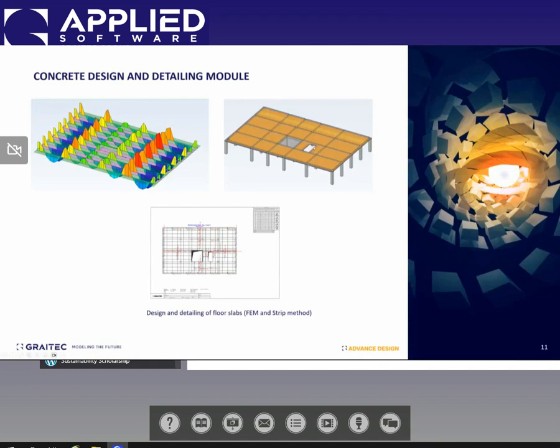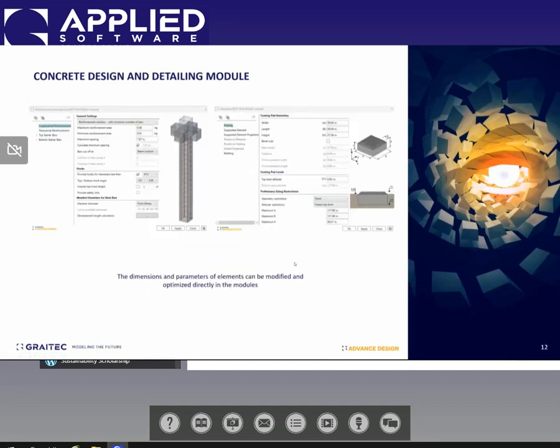And as you see, the software will automatically detect all of our openings and put specific rebars around the openings. And down below here, same as the other components we discussed, we can also create the drawings of this floor slab as well as the bar schedule. So as we discussed, Advanced Design can automatically create those rebars for you in those elements.